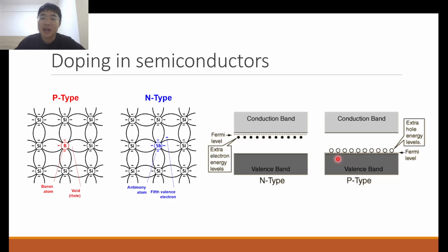Because you can think of, let's say, electrons can move freely in the conduction band because it is effectively full of empty states where the electrons can move to. So if hole is the converse, that means holes can move freely in the valence band, where they are full of electrons to move to occupied space, therefore effectively moving the hole.